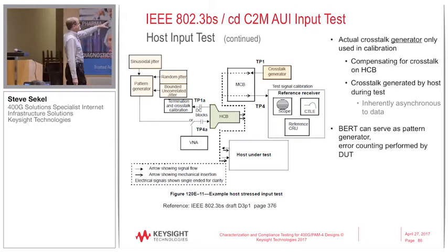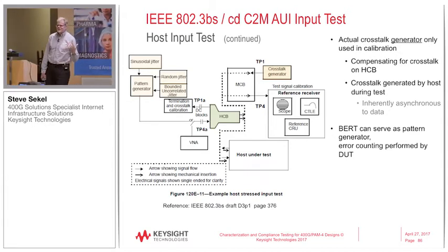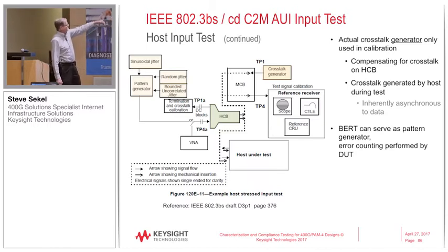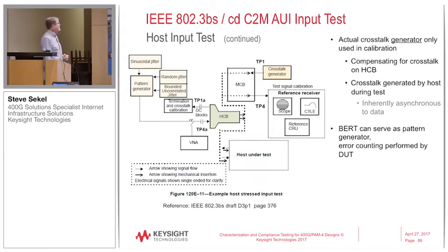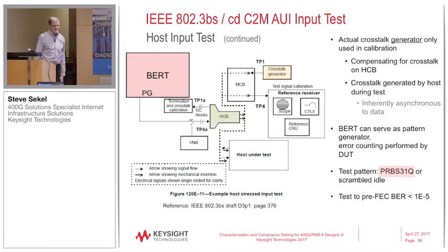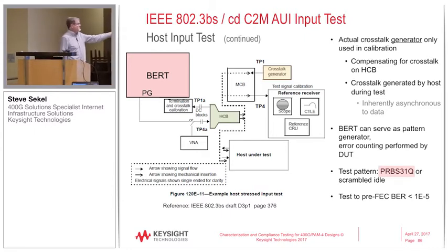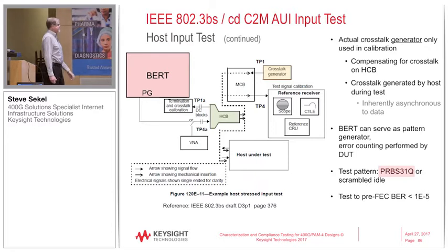They've been using the same parts of the same drawing for almost 20 years now, and we didn't even have stressed BERTs when they started doing so. That's why they typically show a pattern generator with an FM synthesizer off to the side, and you can just think of all of that being replaced by a BERT. All the modern BERTs from all the vendors have all those stresses built into them, and that's the instrument you use to run the test.